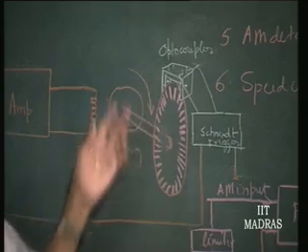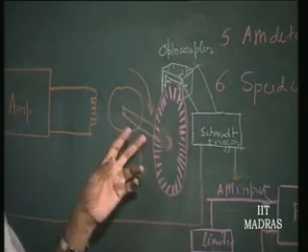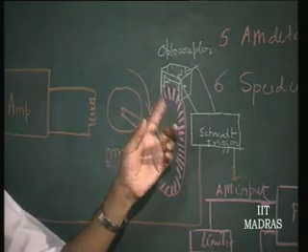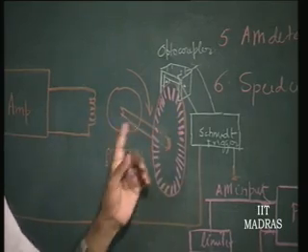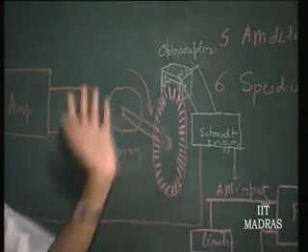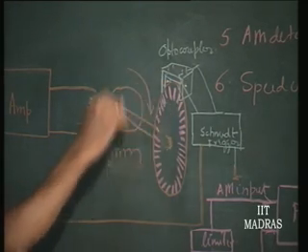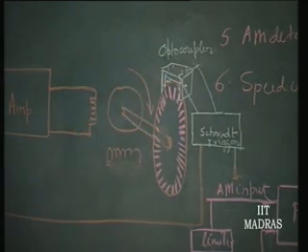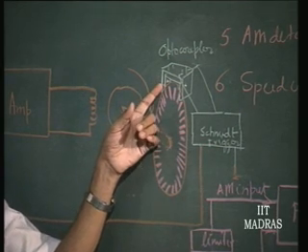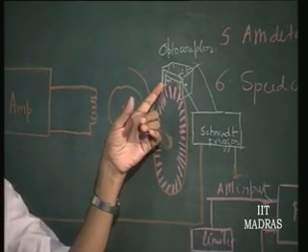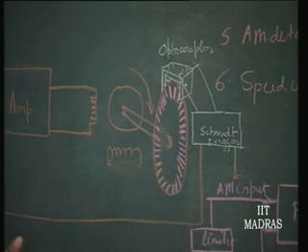Okay. So, these discs also can be made by using what is called photolithography technique, so that you have slots cut exactly equidistant around the circumference. So, what happens as this rotates, the light will be cut off or permitted depending upon whether the slot is right in front of the beam or not, right.